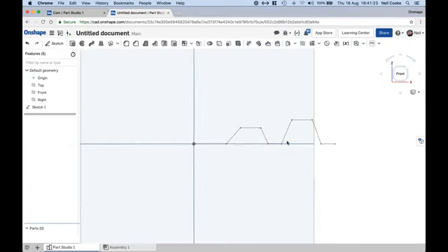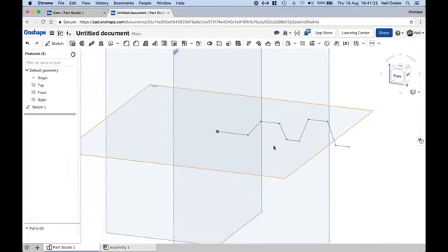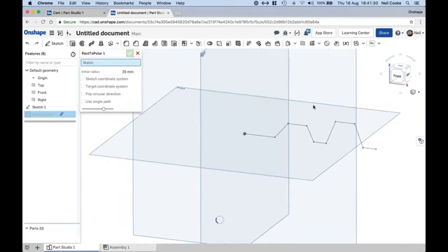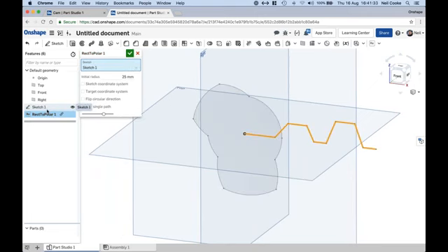So just from a simple sketch which defines the profile of the follower, you can then use this custom feature to define that. So just hitting the sketch button, okay, we'll define that cam for me. You can see it's a little bit crazy. Now, a couple of things that's happening here is that the initial radius here set to 25 millimeters is what we can see here. It's essentially in the z direction of this sketch, it's 0 here, but it's 25 plus 0. Okay, so perhaps you want that going from 25 to 35. So it's a little bit crazy.